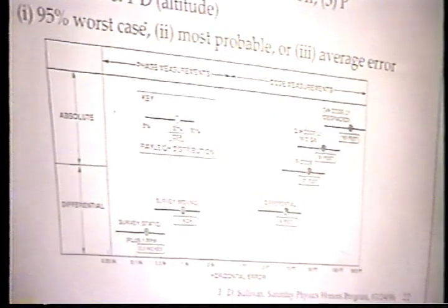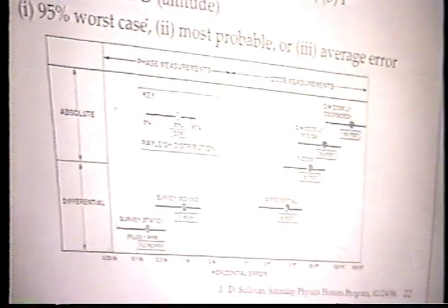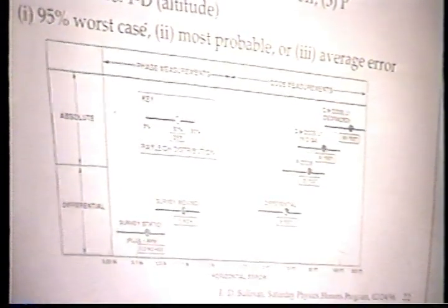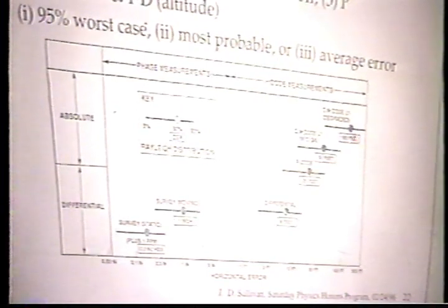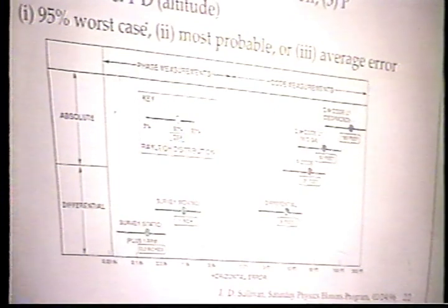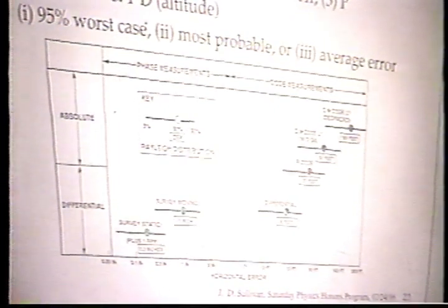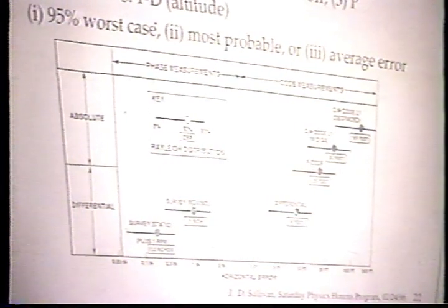Absolute accuracy means where you are with respect to some fixed coordinate system. When you're using the clear or the acquisition code, which is what the cheapest receivers used, and they're degraded by having selective availability on, the average accuracy is 165 feet, but there are error bars on it. It can be as low as about 50 feet, but you only get that about 5% of the time, and it can be much worse. It could be more than 300 feet inaccurate.